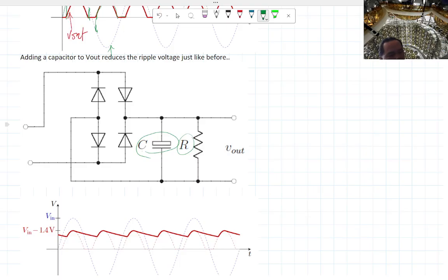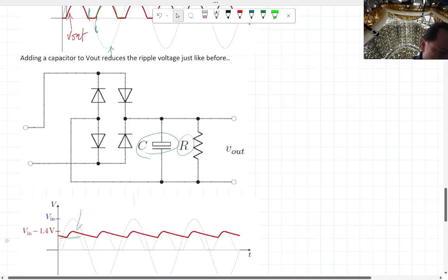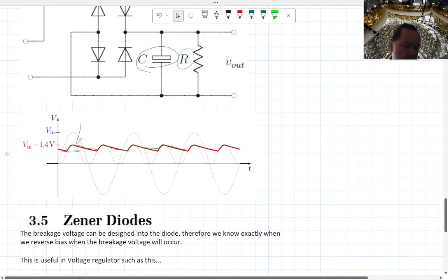Typically, the larger the capacitor, the less ripple there will be, but then the bigger and heavier it'll be. So that's why if you have something that has a very tight tolerance, you actually have a big capacitor on it, and therefore it reduces this ripple situation. We're going to get to see this in the lab and calculate it. And similarly, if you put this capacitor in here, it smooths out with this exponential decay between the up and down swing of your AC source.